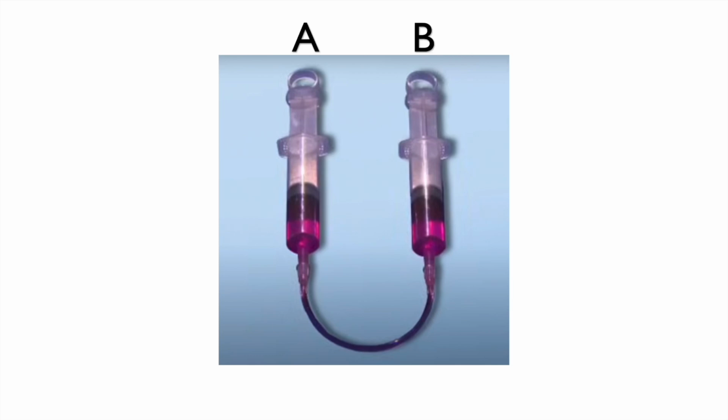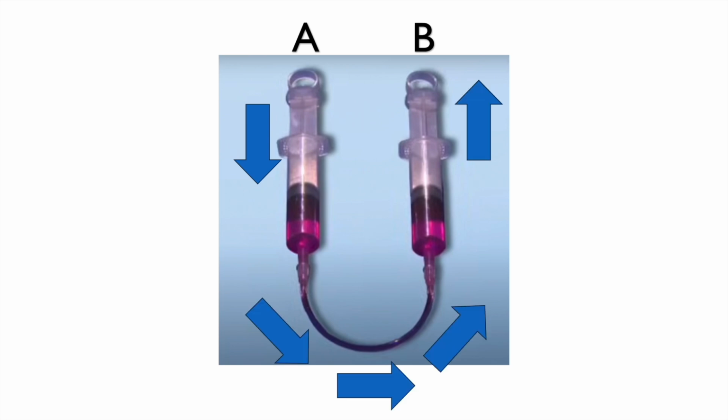Let's imagine we have 2 syringes that are connected by a tube. Inside this tube is water that connects both of these syringes. If we press down one of these syringes, we will see that water will move along the tube and the other syringe will appear to extend. This is because when a force is applied to the water, that pressure will be seen in all parts of the water. However, this principle won't hold if there's air in the system. That is because air is once again compressible, so the system must be airtight.